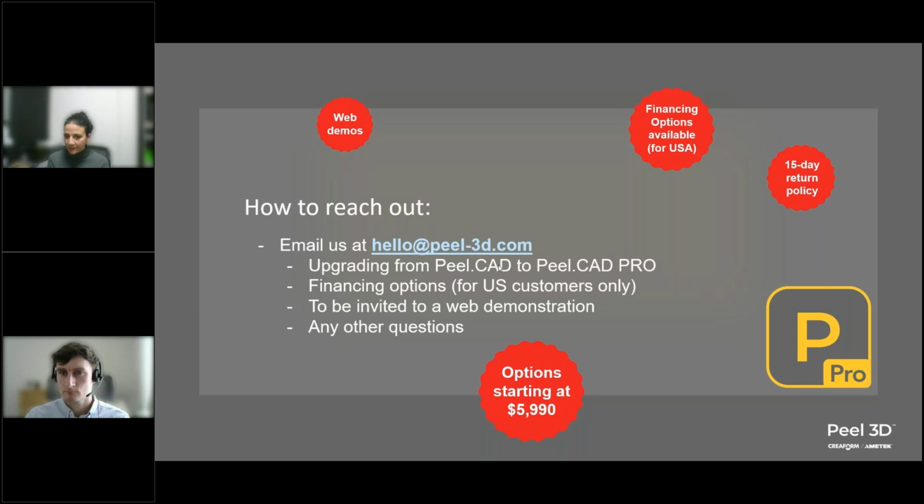And I actually don't have that value on me right now. Maybe Marcio, if you happen to have that accuracy value somewhere, could you let us know what the volumetric accuracy is? Yeah, the volumetric accuracy is 0.1 millimeter per meter plus the 50 microns. That's the same value for the entire scan.